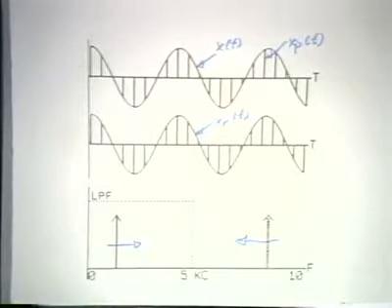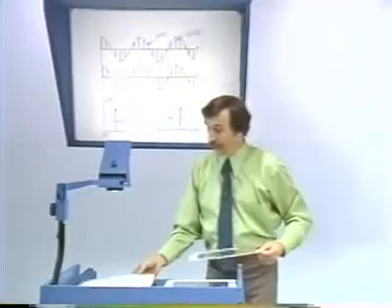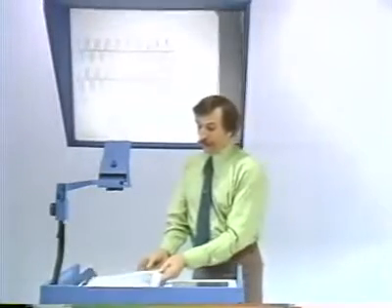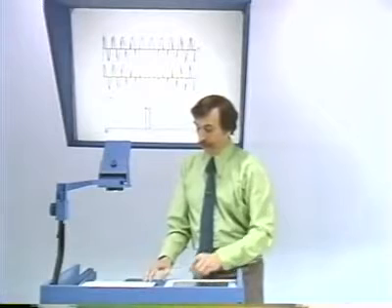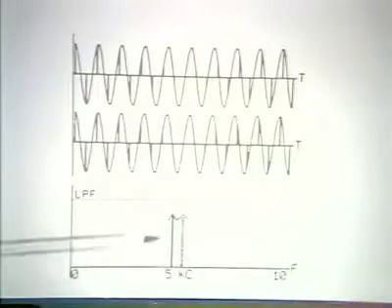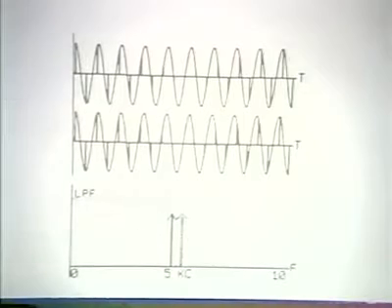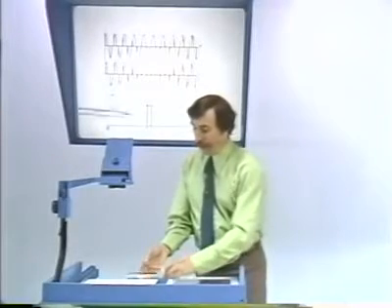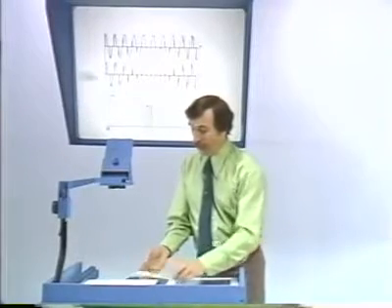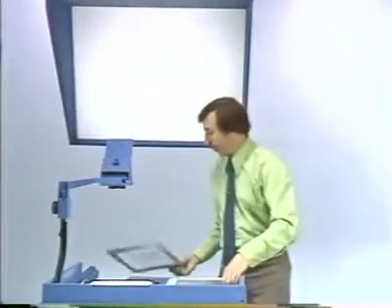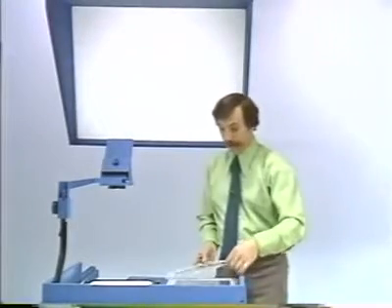And so let's just look at a few frames as the input frequency increases. So we have here a case where the input frequency has moved up close to 5 kilohertz. As we continue further, these two impulses will cross, and what we'll end up with, as I indicated, is aliasing.